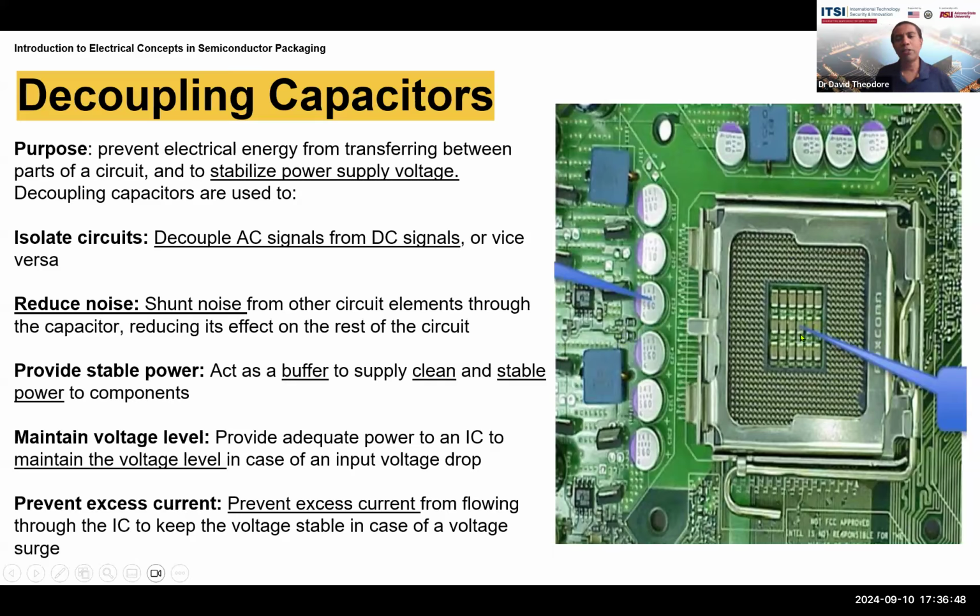Ceramic capacitors are better for high frequency operation, and they're also more efficient, and they are smaller, which is good, but they're more expensive than the electrolytic capacitors. So here are capacitors that are part of the power supply for the chip, intended to smooth the power that's coming to the chip, to smooth the voltage and so forth.